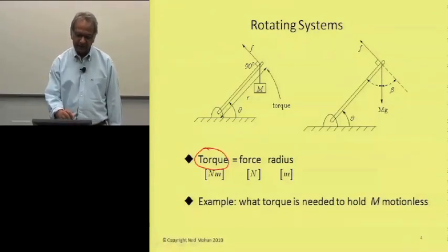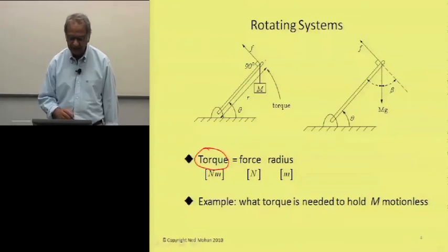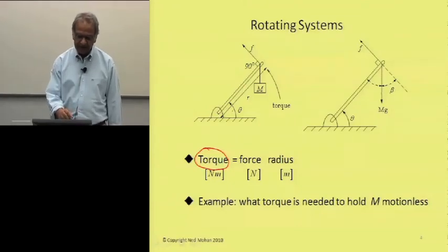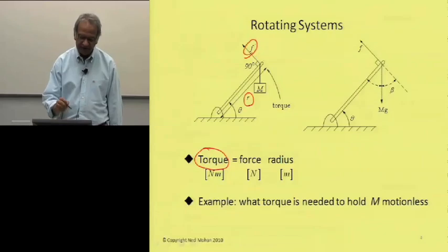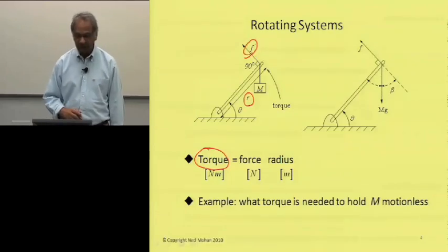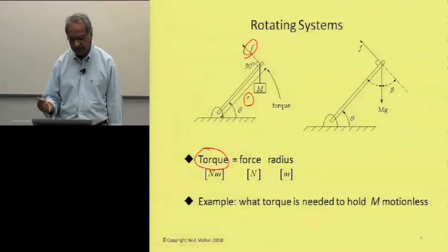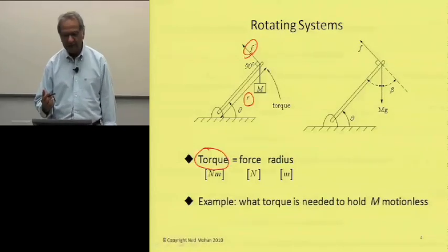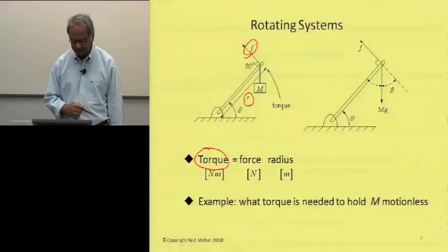You have this lever arm, and its length or radius, let's say, is r, and a force perpendicular to this arm is acting here, then the torque is really r times F. Or, if it's not perpendicular, then it's really the perpendicular component of that force.